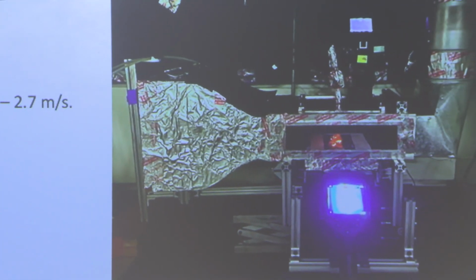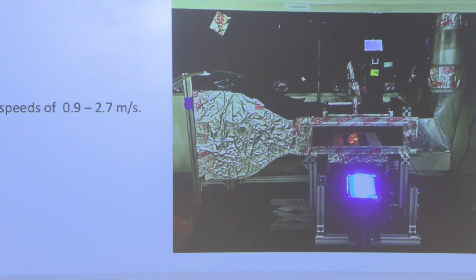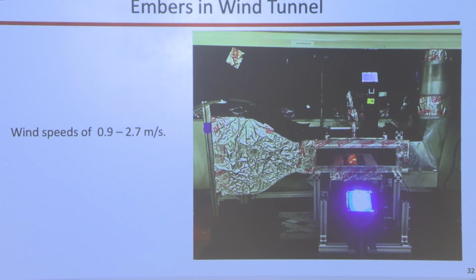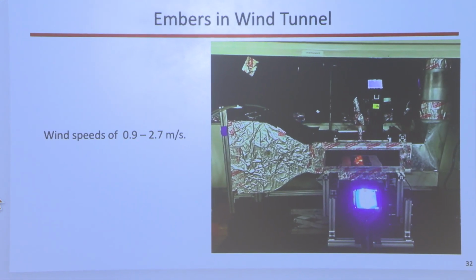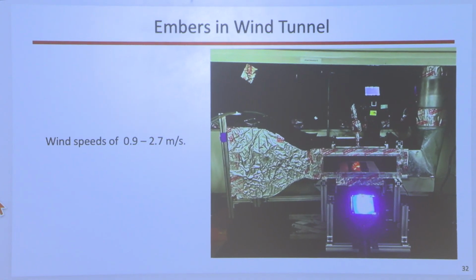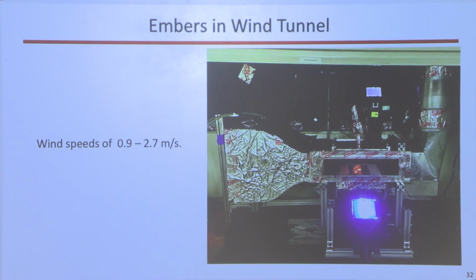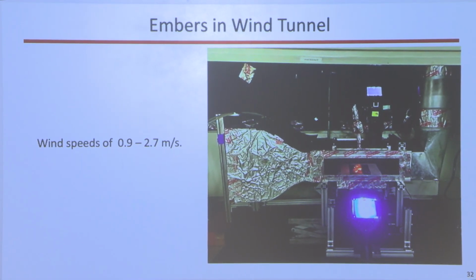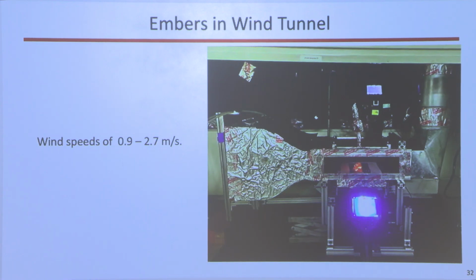So in this case, we did the measurements in a wind tunnel, instead of doing it with the case fan. Here the flow is from the left to the right, and you can see the screen of our infrared camera in front, and just above that the glowing embers. So it's an ember pile. We cook these same kind of dowels over a big propane flame and then pour them into the wind tunnel, seal up the wind tunnel with the window, and start taking pictures of the overhead view. The overhead view there is with the Sony camera that's going to do the pyrometry.